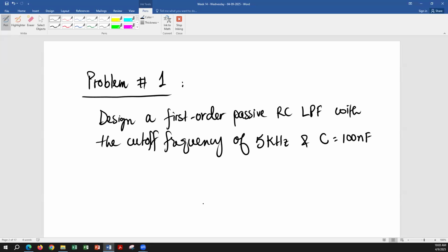Generally, in between, like in kilo ohms or high 100 ohms, those values are good to use for resistors. They are more stable, and tolerances are also better for those values. But anyways, let's see for 100 nanofarad, what value of R we're going to get. If it is too small or extremely large, then we can choose another value of capacitor such that we can find a good, nice value of resistor.